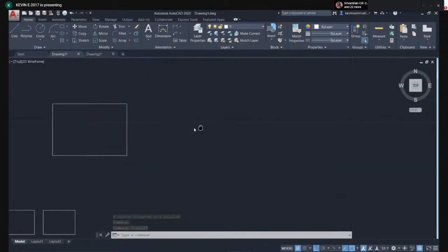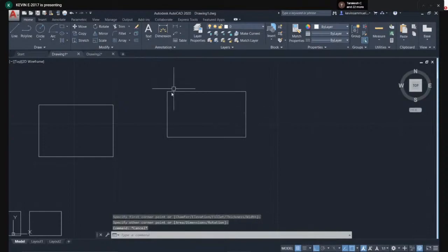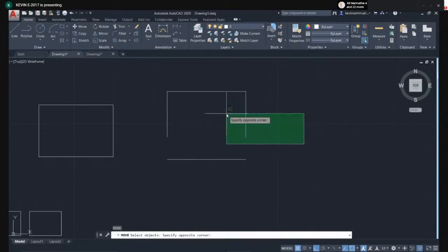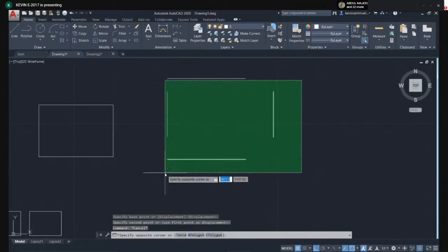And also if you want to do the vice versa, so if my object, again I'm using polyline, if my object is a whole object, a single entity, and I want to break it into individual objects, I'll select the object and press explode, EX. You can see here explode. And all these lines will go back to single individual lines. You can also move them. They'll just become single individual lines again. So that's what join and explode will do.